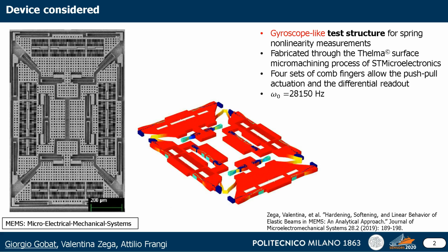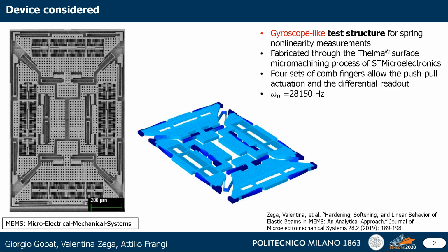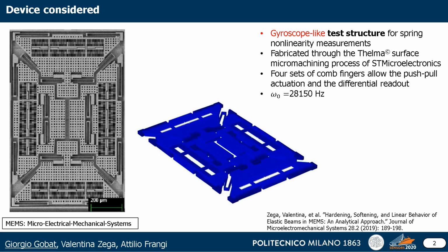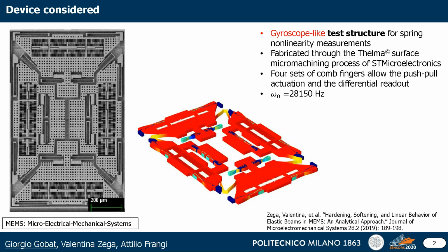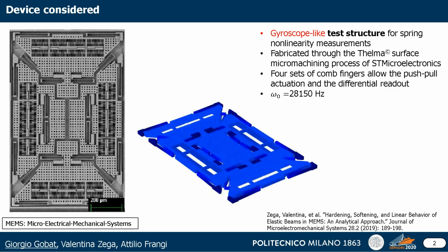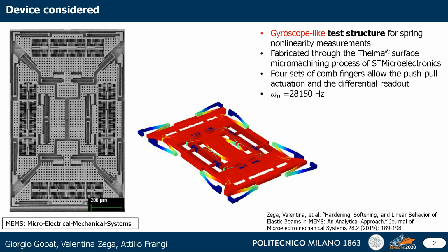The device is fabricated with surface micromachining and it is excited through comb drives placed on the four shuttle masses. The electrostatic force induces a beating heart motion, named drive mode and shown in the animation. The drive frequency is expected around 28 kHz.